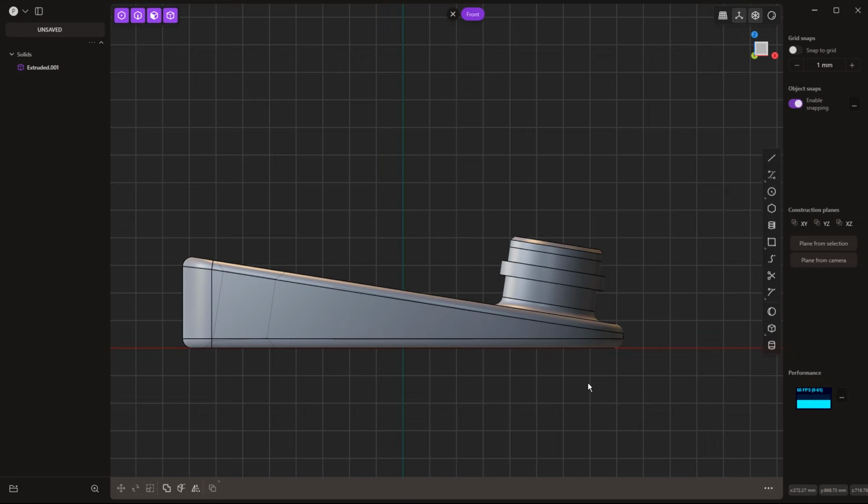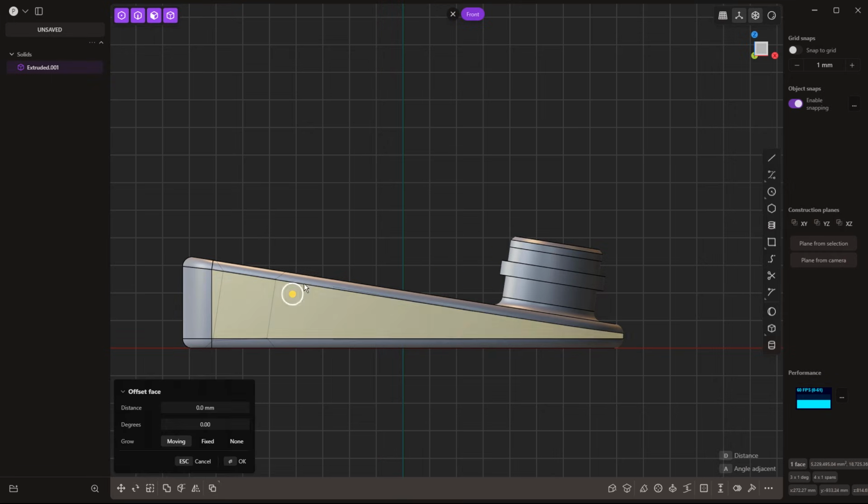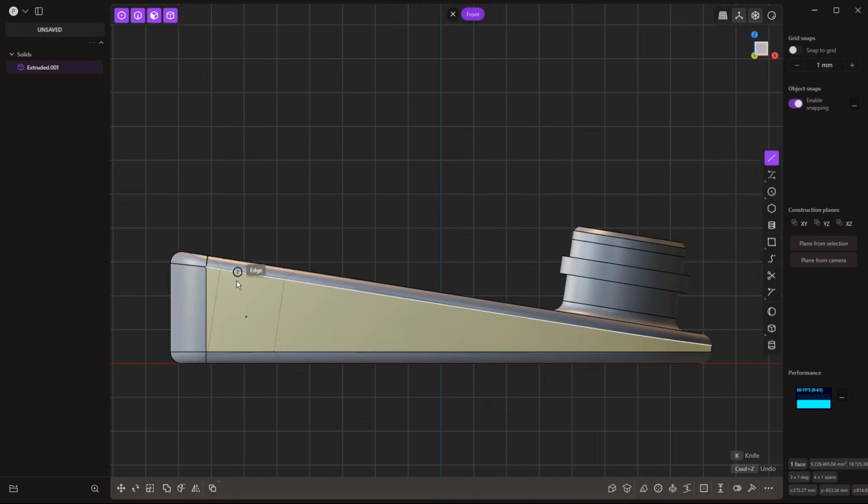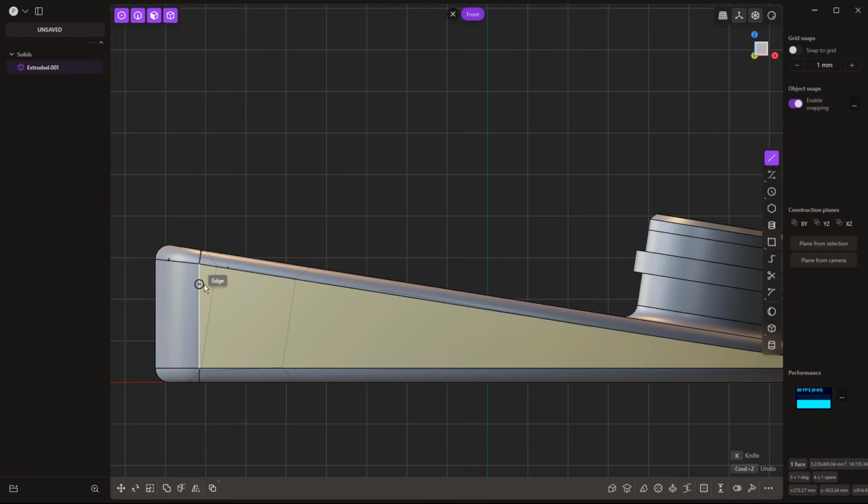The next thing that I want to do is create a cut going through the side. And there are a couple of different ways that we can do this. Now, one way is for us to take the profile of the side face and project it to that center section, offset it, and then we can use it to create that cut. We could also do this directly by hitting O and creating an offset of that face, or we can start to create new curves.